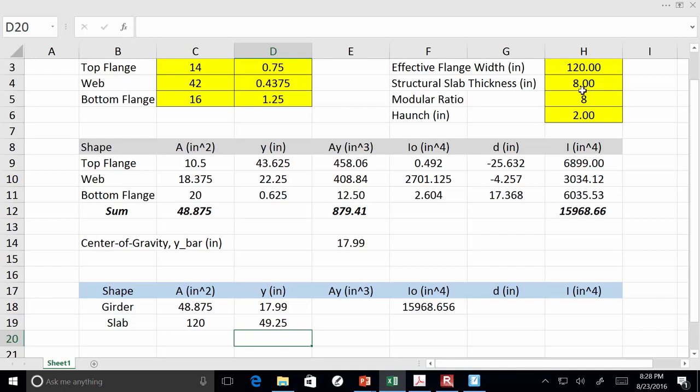And while we're at it, why don't we go ahead and fill this in? Okay? So moment of inertia. So width times height cubed over 12. But what do we got to do to the width? Divide by 8. So equals, and I'm going to use parentheses, we're going to do the width divided by 8. Then we're going to do times the thickness cubed divided by 12.